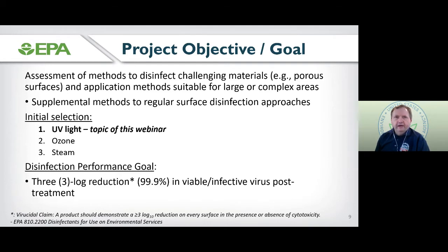We identified upfront a disinfection performance goal. That was a 3-log reduction, which is equivalent to a 99.9% reduction in viable infective virus post treatment of the specific decontaminants of choice, UVC, in this presentation.